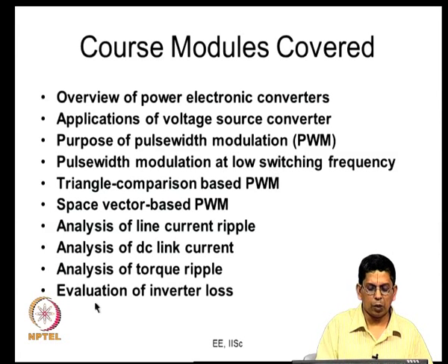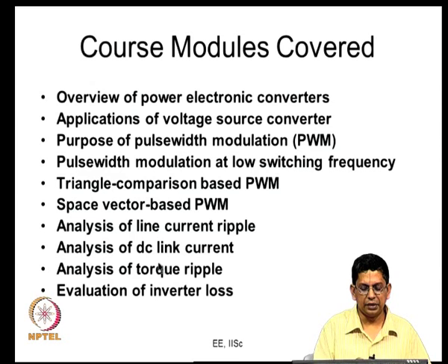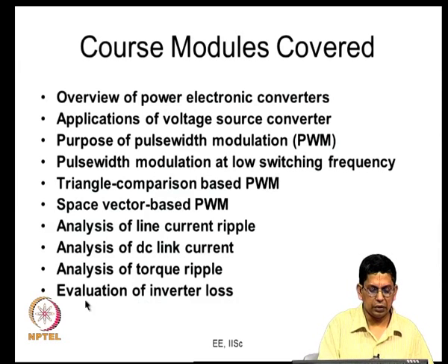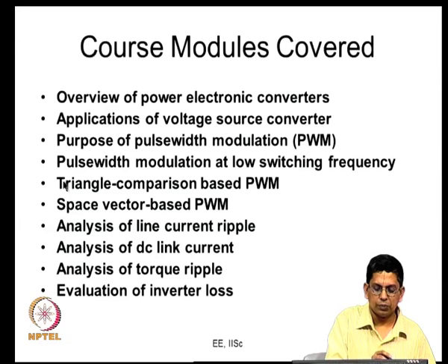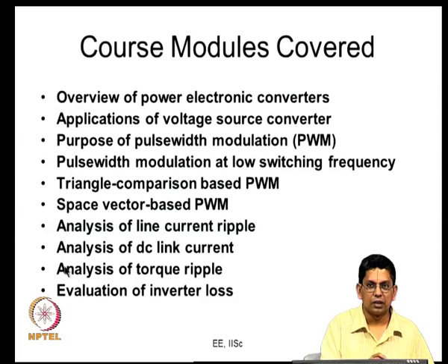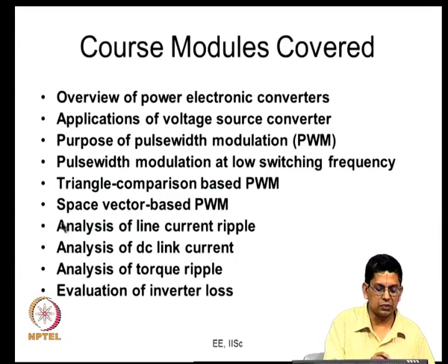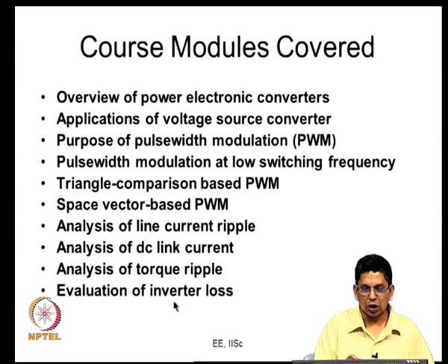So, they were where we wanted to analyze the line current ripple, the DC link current and the torque ripple. Then subsequently we have started looking at... in some sense I would say when you are generating PWM, your focus is on the fundamental, and in these modules your focus is on the harmonics, the non-sinusoidal components which are there in the inverter output. And now we are moving on to certain non-idealities.